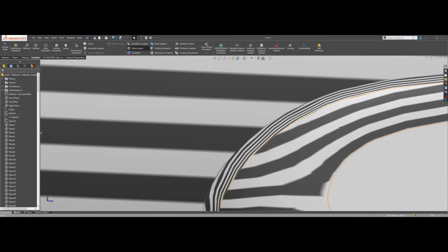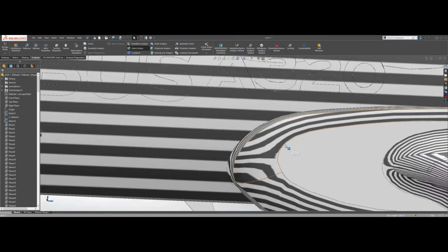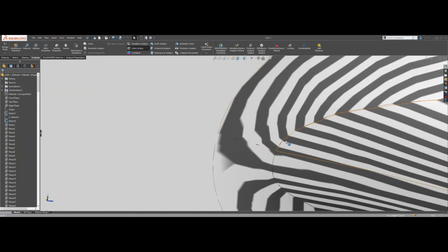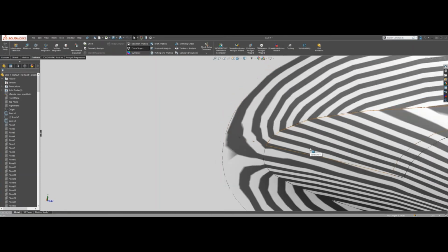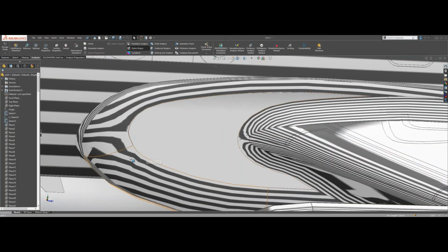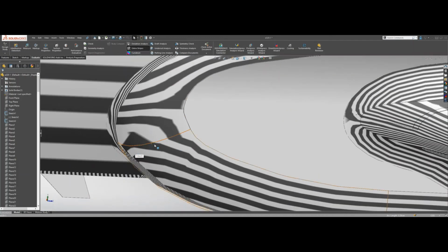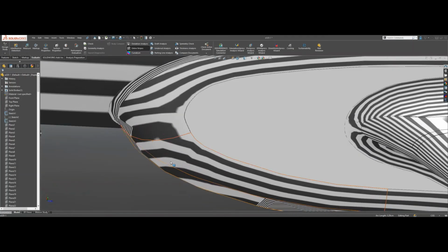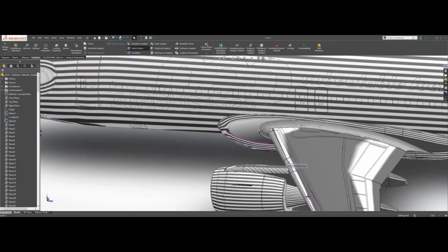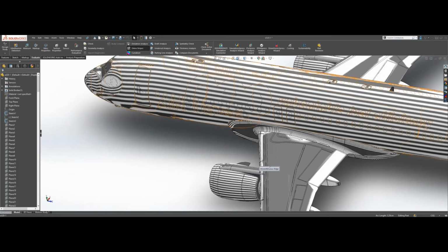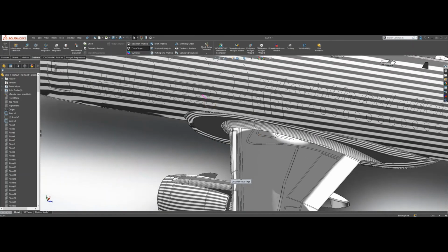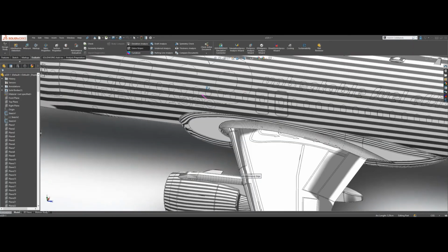Let me just erase all these different drawings and go back to the normal drawing mode. Okay, and then you can see here, once again, how it goes from one face to the other one, and it's actually quite a smooth transition. Okay, and so on. Perhaps other ones we could have not a smooth transition, so it perhaps could be some tangency. But what is cool is that as you move your view, right, it's going back to sort of how the software defines it. It's just trying to reflect long strips of light onto your surfaces, okay, to help you analyze them.